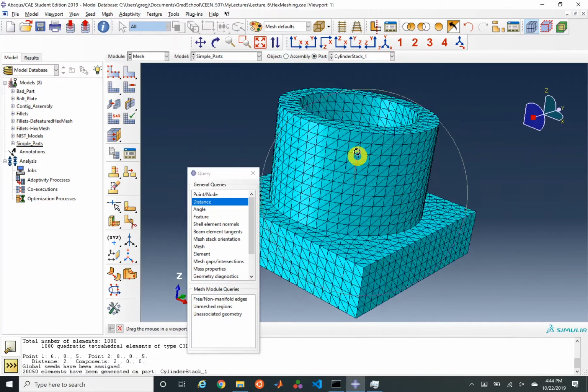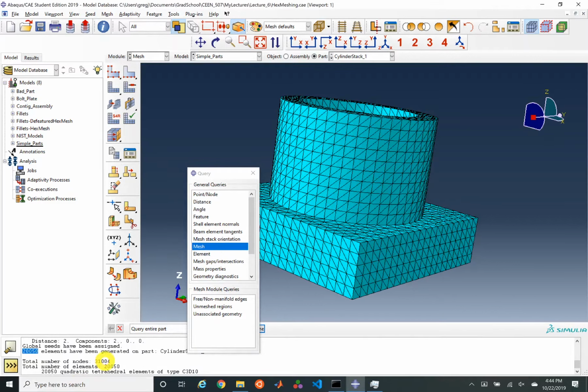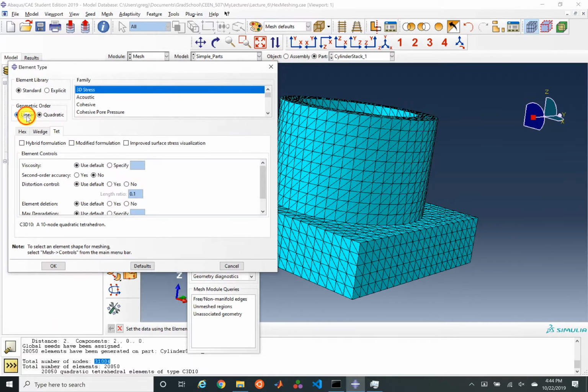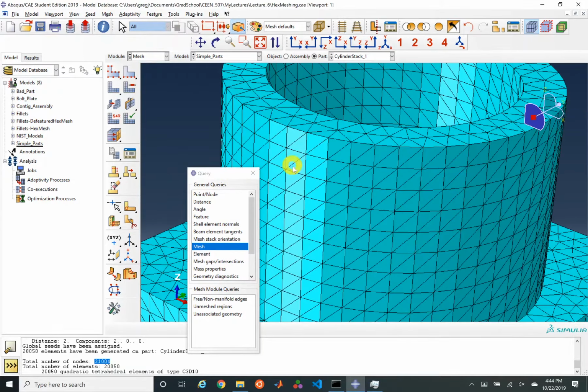on this top. Now obviously we've got maybe more elements down here that we need, but we can just see that we've got maybe now 20,000 elements. If we query the mesh, we have about 31,000 nodes. And just compare now, if we were to say instead that this could be a linear tet mesh. So now we see the curvature's gone away. That this goes down to 4,000 nodes. So just notice that swapping between a linear tet mesh to a quadratic tet mesh is almost a factor of 10 from the degrees of freedom that we've had to add to our system.